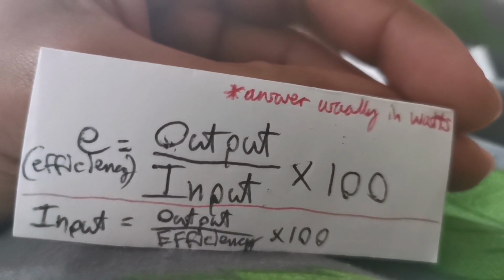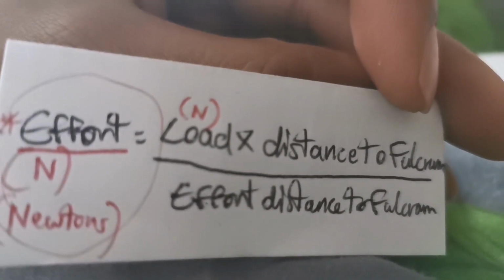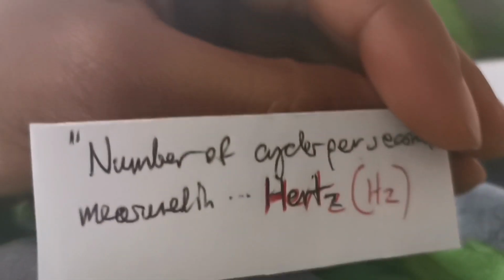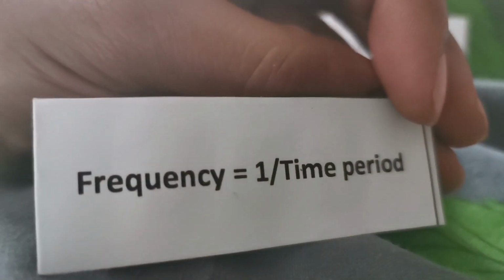So, if I have a cable with a resistance of 10 ohms, and I double its length and remeasure its resistance, its new resistance will be 20 ohms. If I take the same cable with a resistance of 10 ohms and halve its length and remeasure its resistance, its new resistance is 5 ohms. They are proportional. Double it, double the size of resistance; halve it, half the size of resistance.